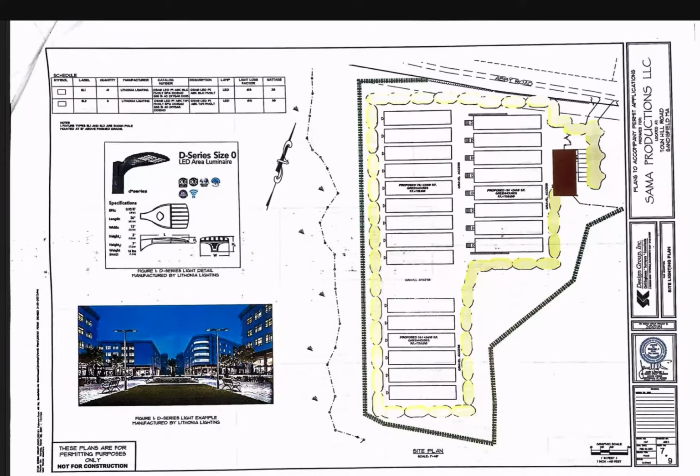If you need any other lighting, by sensor, typically you have some just downcast lighting that can be put on the building itself, in case someone had to run in late at night or something, for safety. All the lights are 15 feet high, so it's a relatively low light pole all the way around the facility. So this is a facility that will light the ground and will not light. There's no light spill. This is all based on manufacturer numbers.